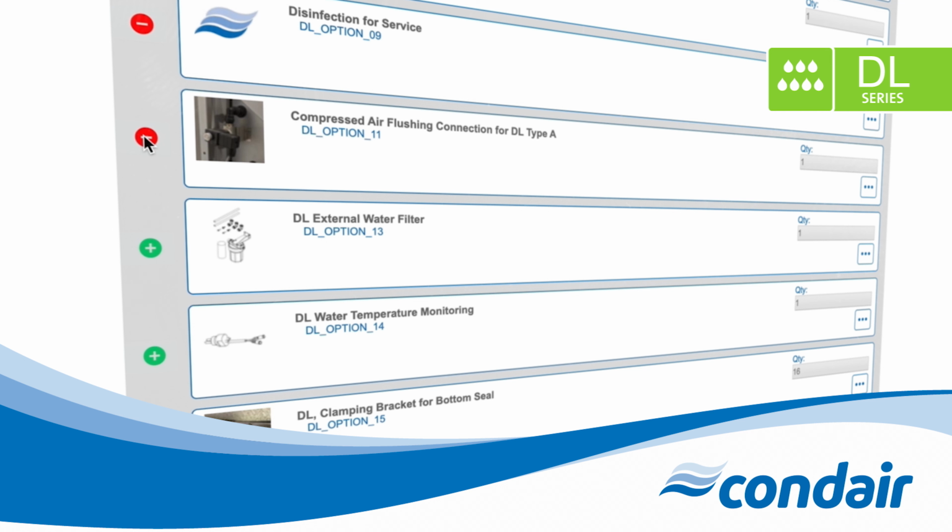Selecting the compressed air flushing option will add additional connection points that allow the hydraulic unit to be cleaned by compressed air flushing. This is good for applications with special hygiene circumstances, such as pharmaceuticals. It's also useful for giving the system a thorough clean before a summer shutdown or during inspections.